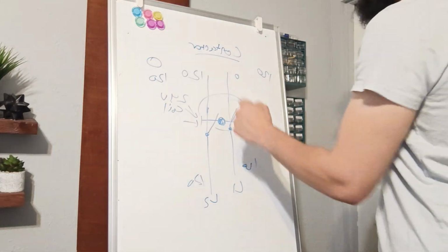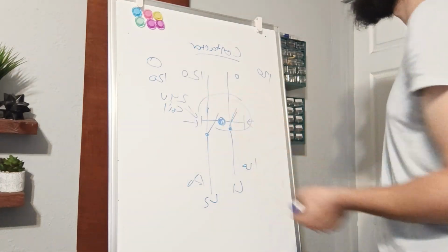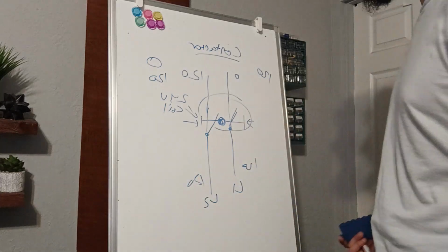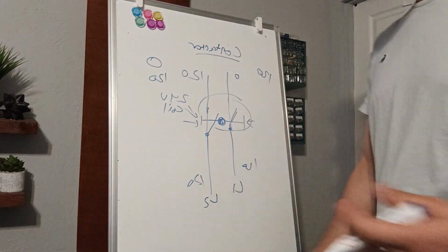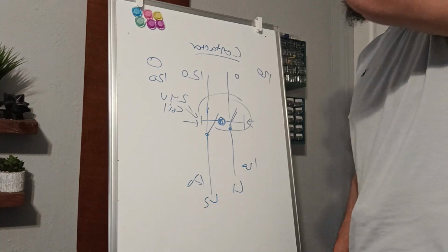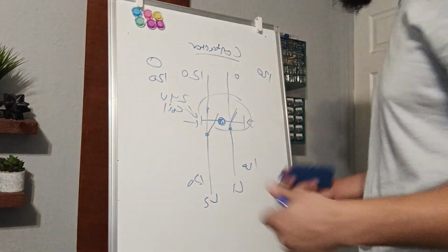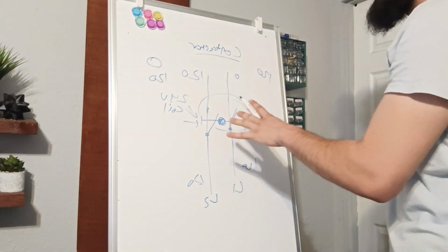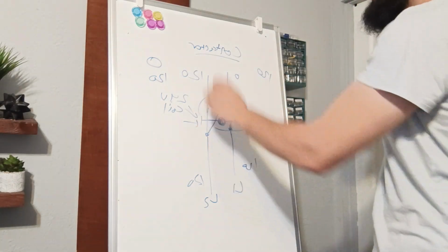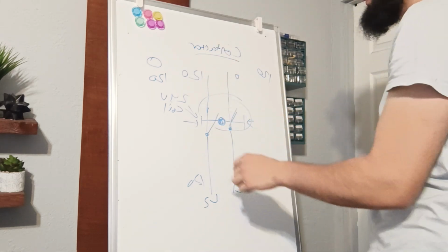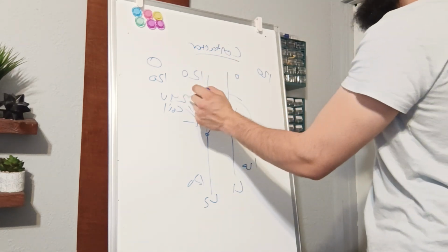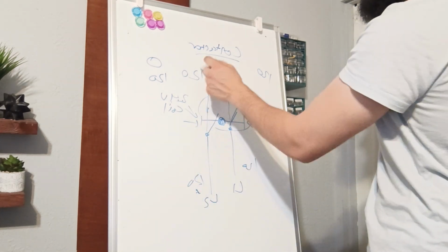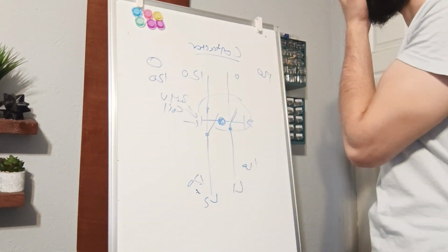If you're not getting 24 volts across it, that means it has a different issue. Perhaps a bad control board, perhaps your high pressure and low pressure switches are triggered, something like that. So for the purposes of this video, a good contactor means 24 volts here, 0 volts across these two points. A bad contactor means 24 volts here, you get a 120 volt reading between these two points on the multimeter.